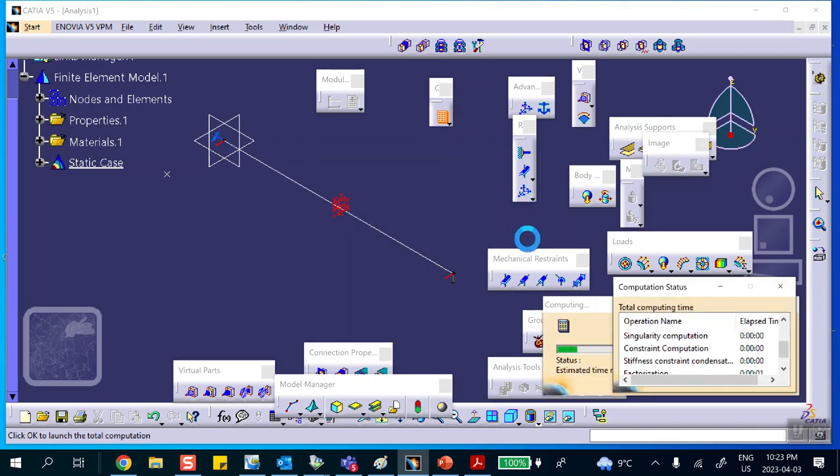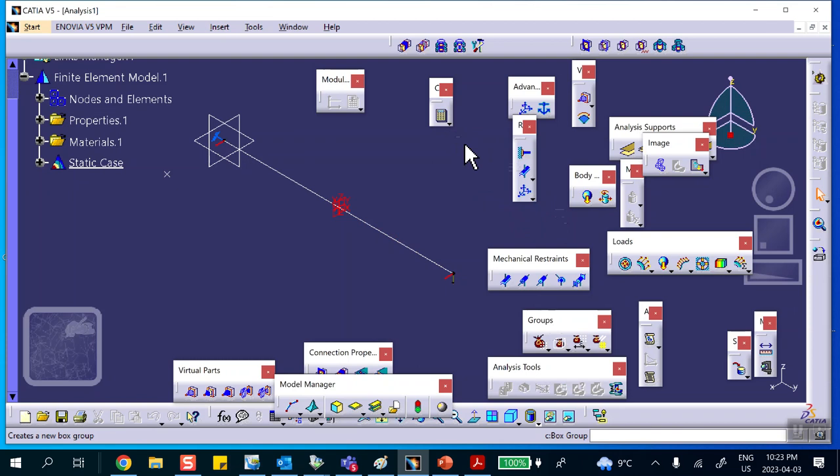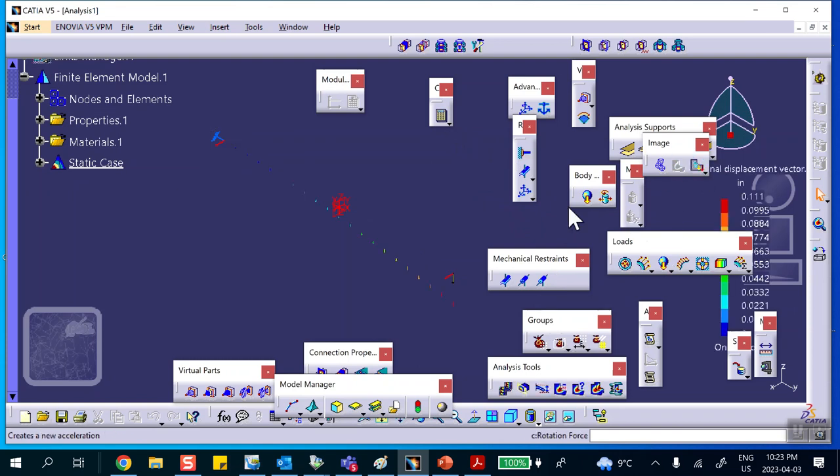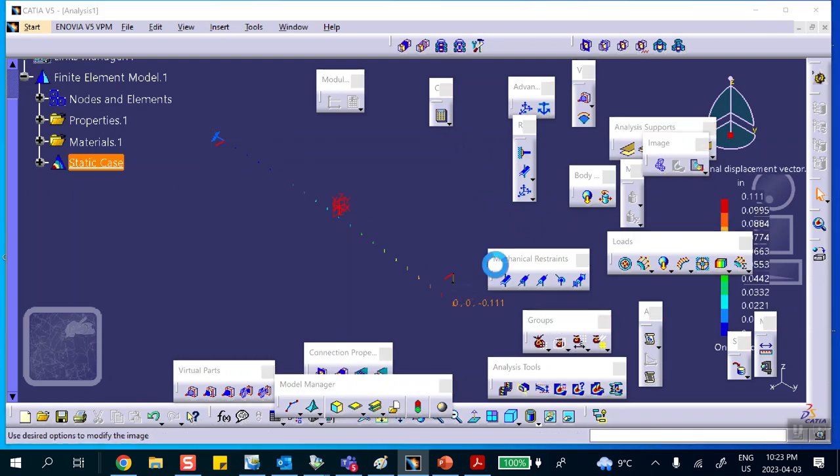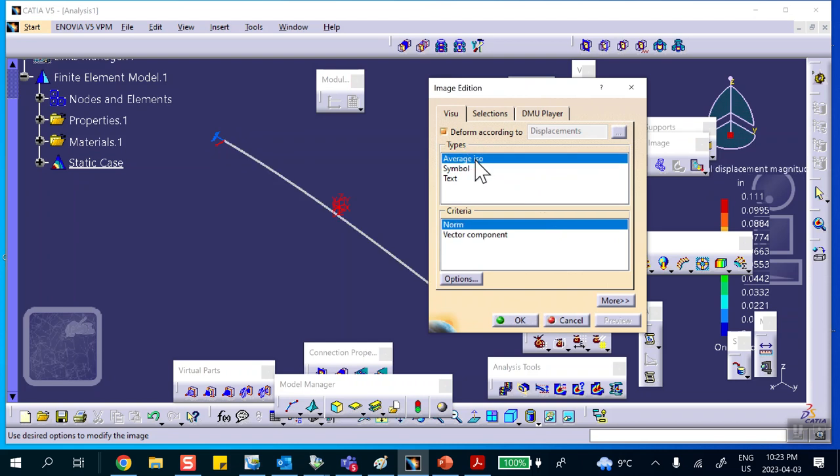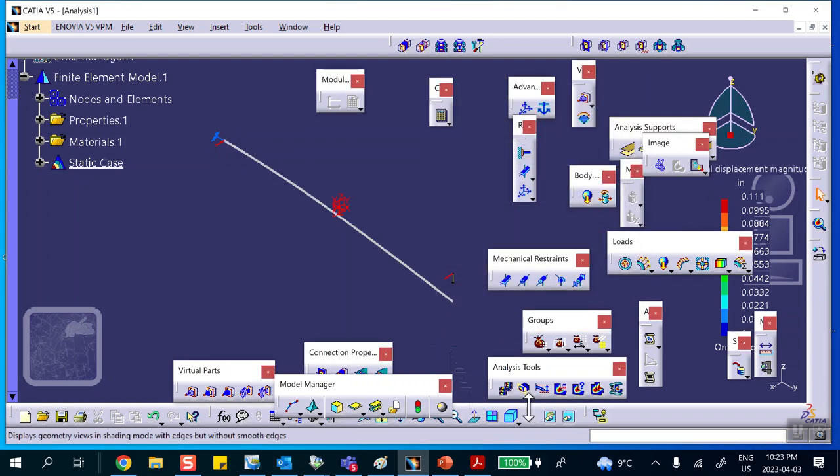Incidentally, you know the maximum deflection is going to be FL cubed over 3EI. That's the standard formula from strength of materials. If I change the rendering here, you can see it better. Yeah, right there, maximum deflection at the tip.